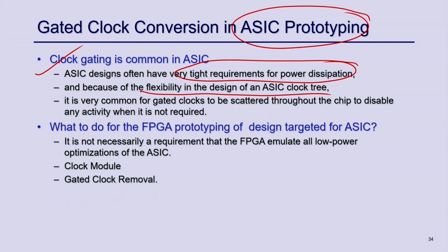Now, think about a circuit of that scale that has a lot of clock gating, and you try to do it in FPGA. Then this clock gating will create a serious problem, right. You cannot map all those clocks to the FPGA board. So, the main thing the FPGA synthesis tool tries to do is gated clock removal. It tries to remove the gated clocks from your circuit, so that the whole design can be synthesizable, because you cannot remove the gated clock from your actual circuit, otherwise the whole purpose is lost, right.